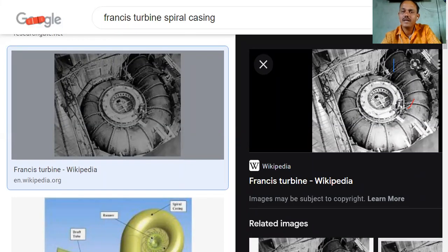Okay, so the guide vanes are like bigger ports, so that the ports can be adjustable. Okay, so these are the Francis turbine, and here in the middle runners are mounted. Now here in this diagram the runner is not present, actually the runner is not installed here, so here the runner will mount. And when water flow takes place from this scroll casing or the spiral casing, it enters from all over.